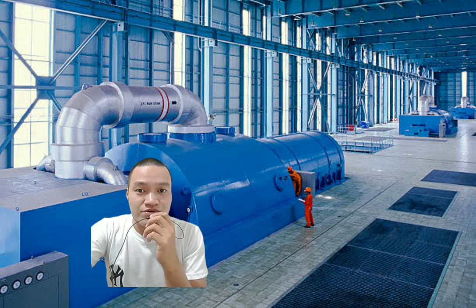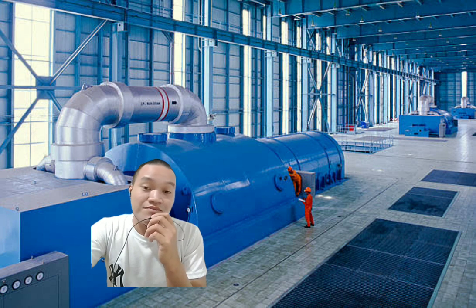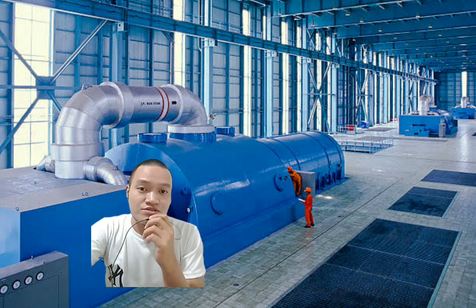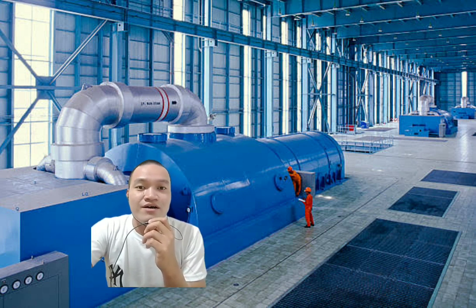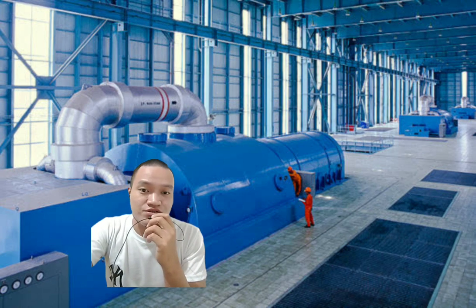Lastly is the operating procedure about port arrival. So we all know that prior to arriving at a port, the bridge should provide notice 1 to 2 hours ahead to be able to enable the turbine to be brought down to maneuvering revolutions. So a diesel generator alternator will have to be started. Then the turbo alternator should be shut down and all the full away procedures must be done in reverse order.